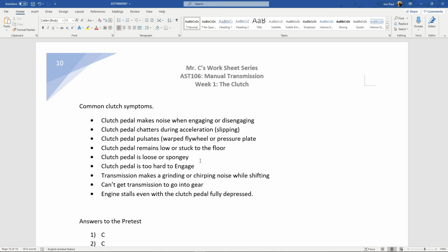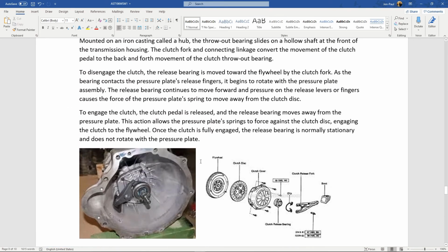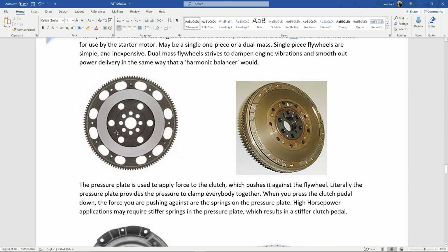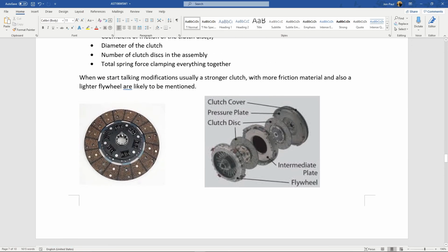What's something that affects the entire transmission as a whole is this clutch. If it's not allowing the engine and transmission, which is really what it's doing, right? It's making the RPM of this crankshaft meet the RPM of the spline on the input shaft, become the same. So if it's slipping or it's got problems, it's not going to do that well.